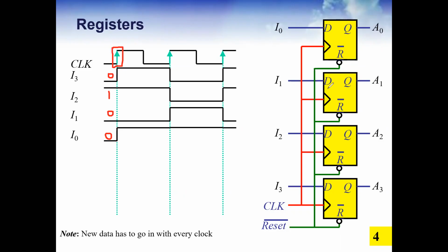Before that, we assume that the flip-flop outputs are 0. It is the initial value. We always assume the initial stored values are 0, 0, 0. But what we are connecting to I3 to I0 is given as 0, 1, 0, 0. But it will not enter the flip-flop until it triggers. So the green highlighted lines here show the triggering moment. At that time, the values will change.